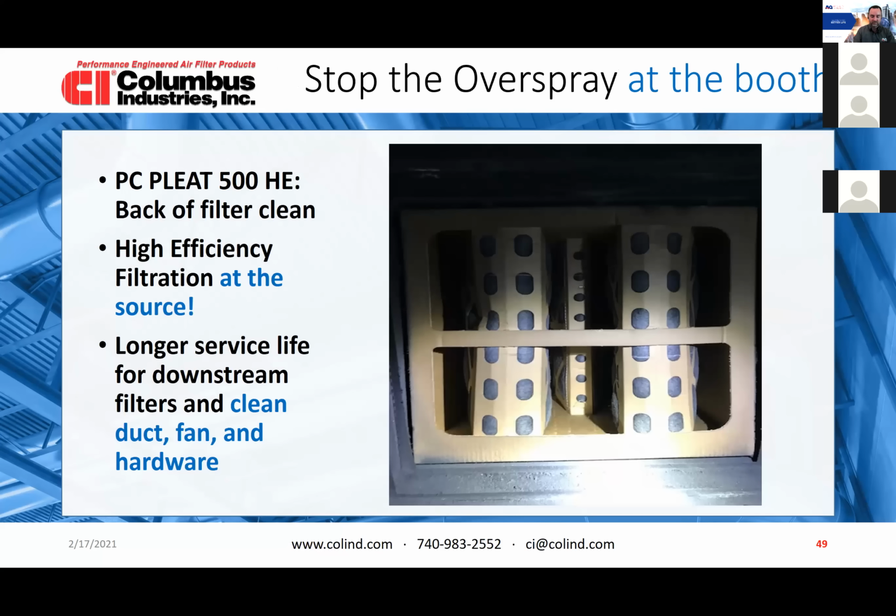Here's the kicker. When we look at the loaded PC Pleat that's about to be taken out, the one that you saw from the front picture, this is what it looks like in the back. You can see how clean the cardboard is right here. There are no particles in there. You can see a little bit on the sides here. That's the finer particles that made it to the pocket. And this is why we could probably relax the front filter a little bit longer to make it last a little longer and make the pocket work more. So it's a compromise between the life of the pocket and the life of the PC Pleat.